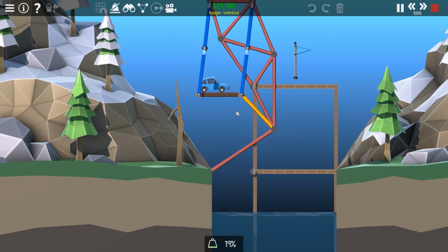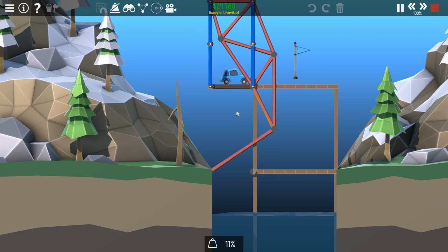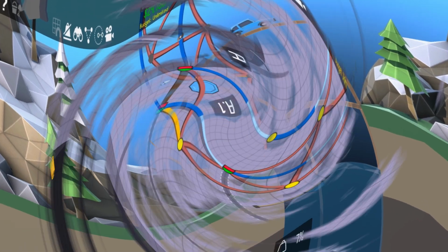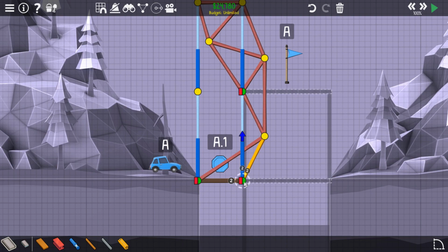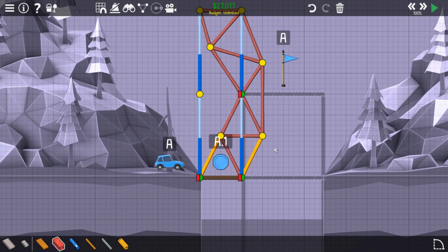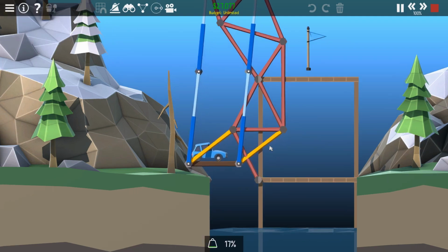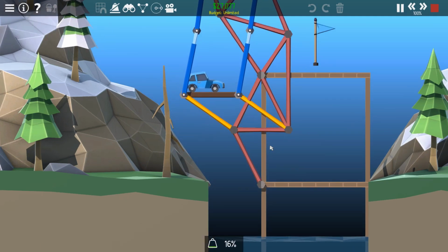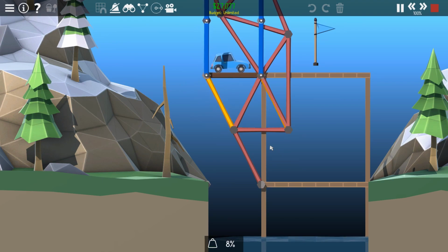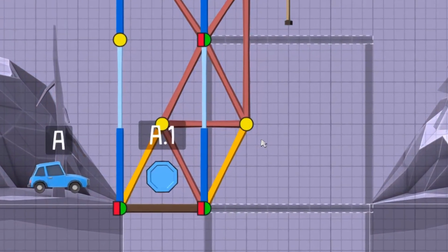We can do better. We are using 4 hydras to lift this, and we can easily cut that number in half. Since we know both ends of the road have to lift the same distance, we can just copy our guiding arm over to the other side of the road. Now when we lift, one end of the guiding arm has constrained the movement of the other so that it follows. We have now braced the other side. Since both sides are braced, they have to follow the same path.